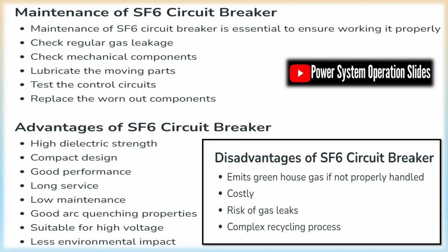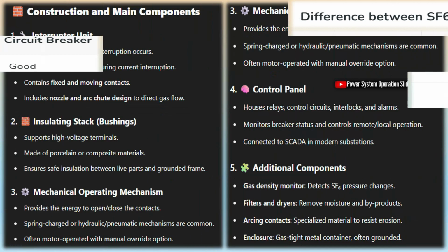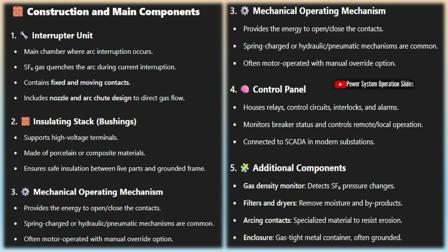There are also several different ways in which the electrical current and resulting arc in an SF6 circuit breaker can be interrupted. These types include double pressure, now obsolete; single pressure, also called puffer; self-blast, where arc energy supports pressure buildup in the arc chamber; rotating arc, which rotates electrodynamically in cool background gas; and double motion technology with two moving contacts. In addition, the drive mechanism of the circuit breaker can be of the hydraulic or spring-loaded type.